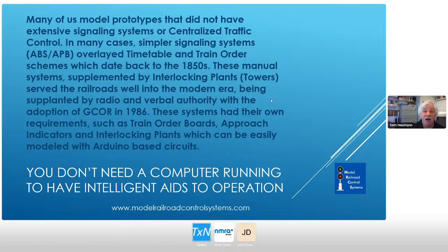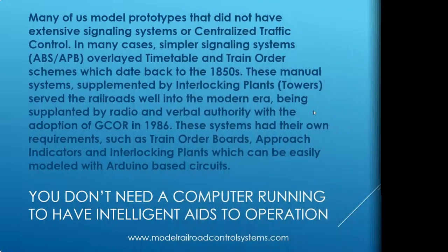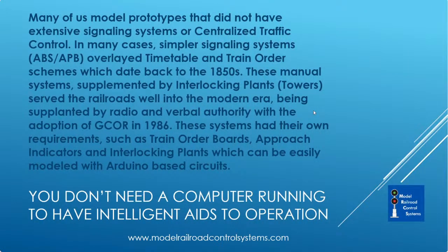You can do this a number of ways, but my preference has been to use small Arduinos on circuit boards that package all of the components needed to solve a particular problem. And this means much less wiring underneath the layout and much easier troubleshooting if you need to swap out a unit.